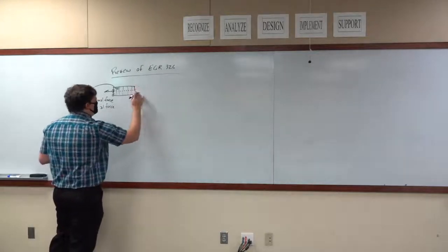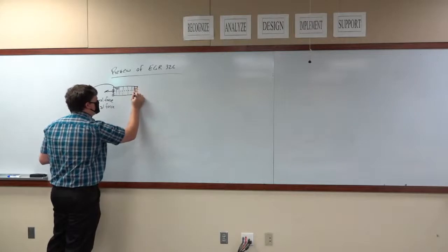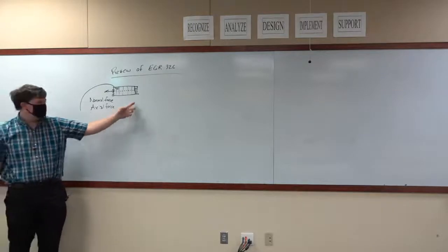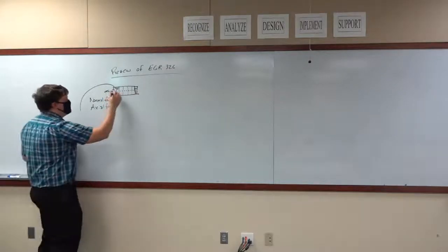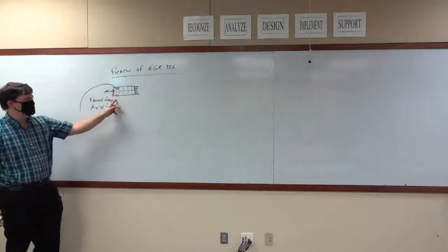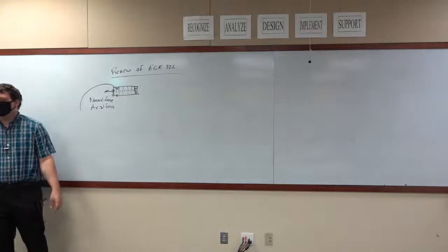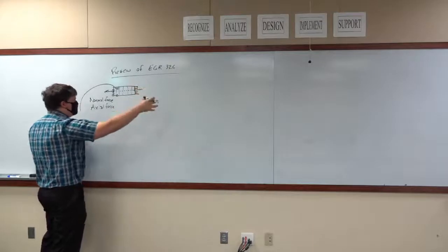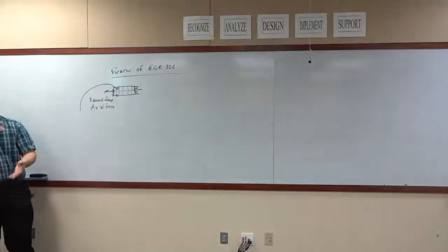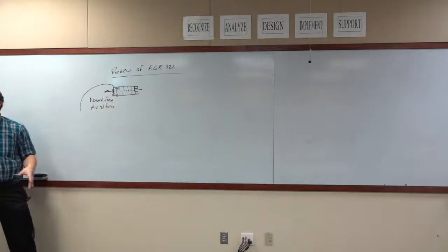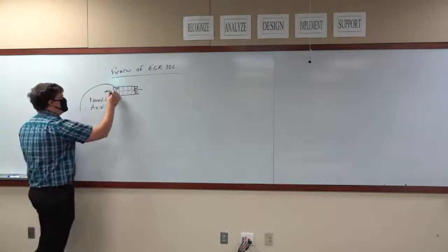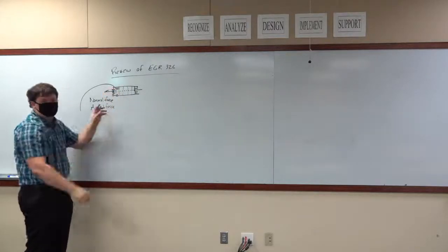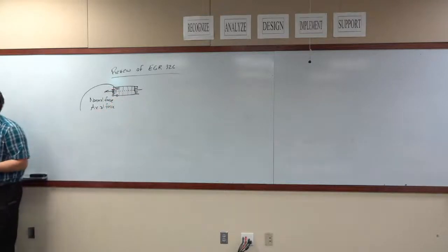Now, if this was a distributed load, where that load was being carried across the entire cross-section, then heck yes, you're going to be seeing a load out in the corner. But unless it's being loaded, that corner isn't going to be facing anything. But we know that about right here, this area is going to be in tension. Now, this varies from material to material, but anytime you have the force being applied through varying cross-sections, it is going to take a little bit in the material for that to transmit. The maximum stress in this component is going to be located right here, at the point of application, because that is where the smallest area is.